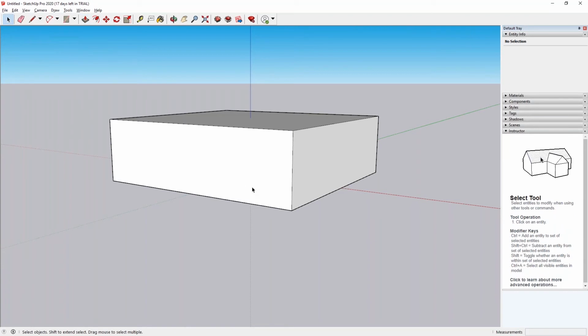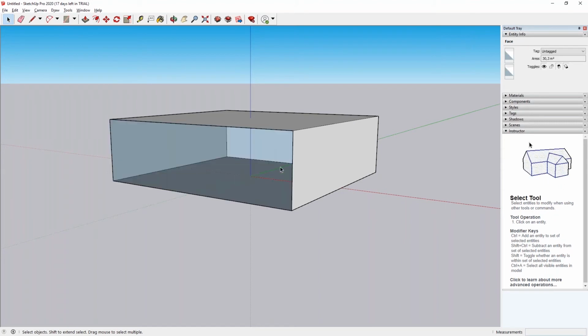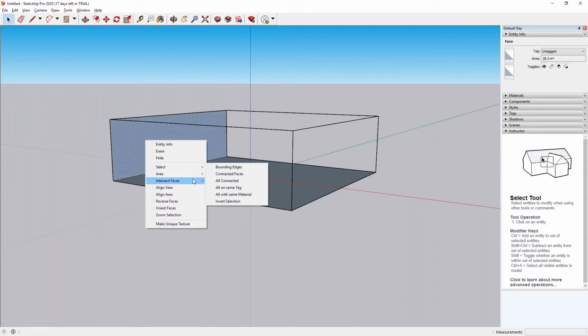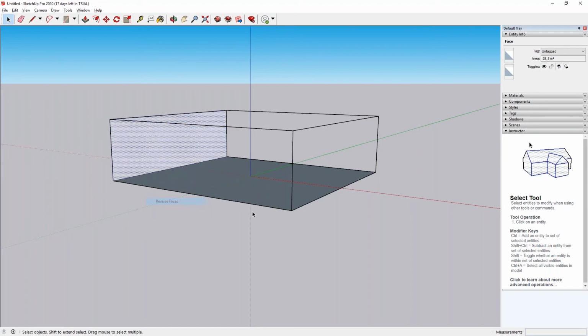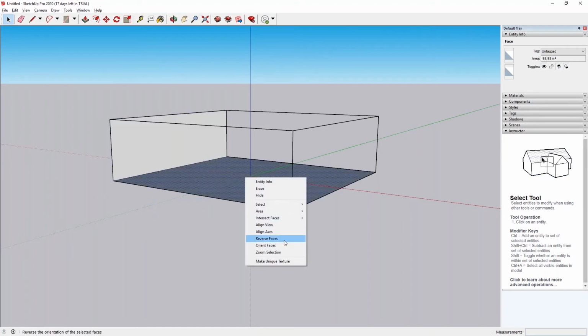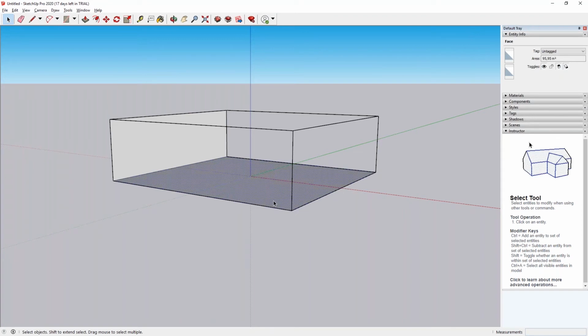I didn't really say what I was making. I was making a room, and we want to be able to see what's inside, because that's where we have measured things. So we delete most of the walls. Just select them and press delete. And then comes this that I mentioned before, that QTM only supports one of the faces, and in this case that is the outside. We want it to be the inside if it's a room. So we reverse it so that we can put a material or an image on this side.